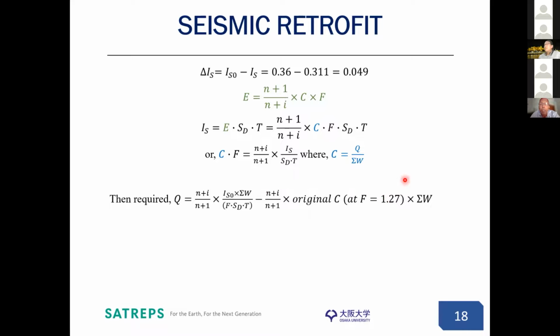So what you select as this is the target of your deformation limit after post-retrofitting. So how do you select that? It's based on the deformation limits allowed by the retrofitting techniques. Each retrofitting technique will give you a maximum allowable F limit. For example, wing wall strengthening might give you a limit of 2.0. For this particular one, as Senshan showed earlier, there are three limits: 1.75 for two types of failure, 1.27 for one type of failure, and 1.0 for column punching.